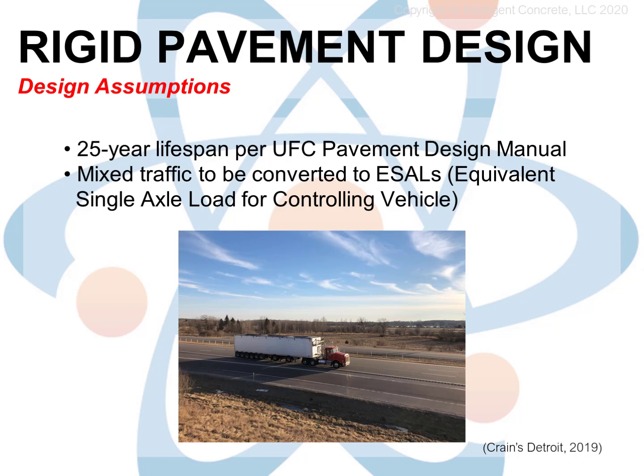Remember that there are many other vehicles which will also use the pavement besides the controlling vehicle. They might be lighter, they might be heavier, there might be many more, there might be less. And they will affect the pavement, but at a different rate and in a different manner than the controlling vehicle. So while not the controlling vehicle, they usually have some influence on a pavement's design. For example, the controlling vehicle might be an 18-wheeler, and we estimate we'll get 100 of them in a day. We might also have passenger vehicles, maybe 10,000 in a day. They are much lighter, but might be traveling at a higher speed.